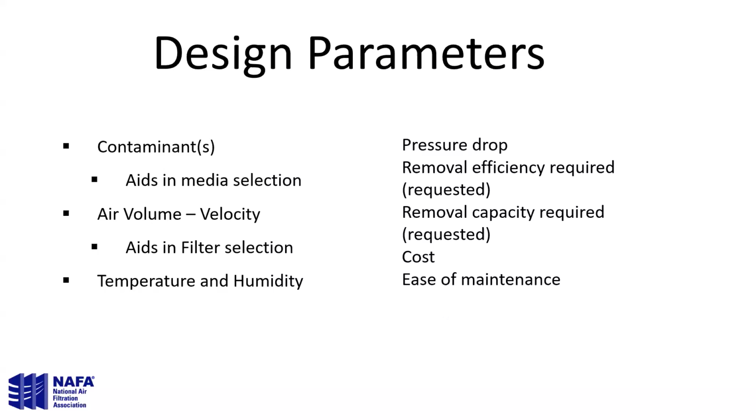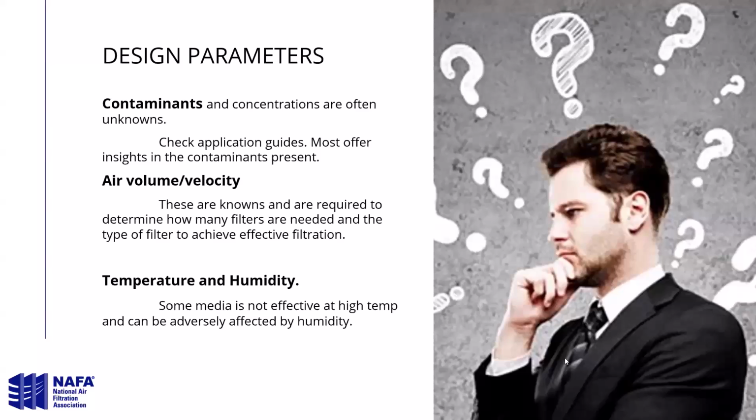I've actually seen jobs ship overseas and filters go, only to find out that the door to the system had a pole in the way. And when they opened it, they couldn't open it all the way, and they couldn't get the filters in, and they had to do all sorts of work to do it. So ease of maintenance, make it easy on your maintenance guy, because then they'll come back and want you to do it again. We'll go on a little further.